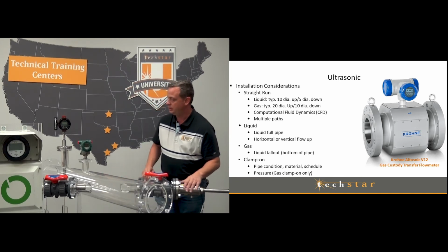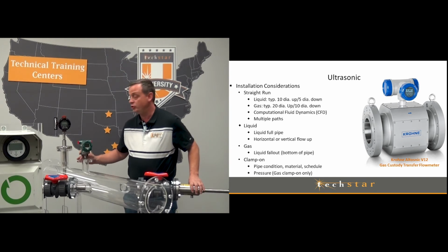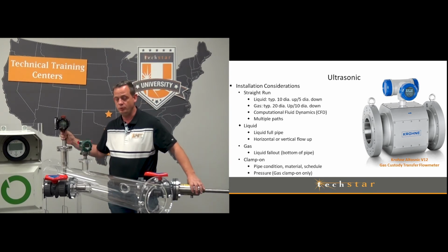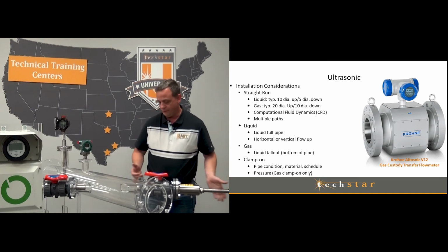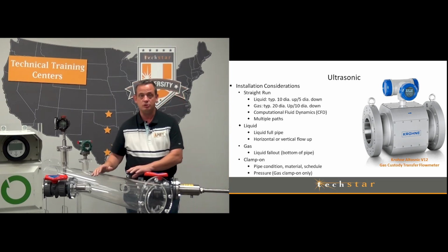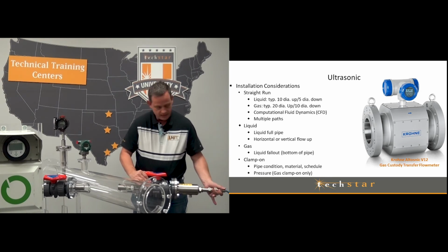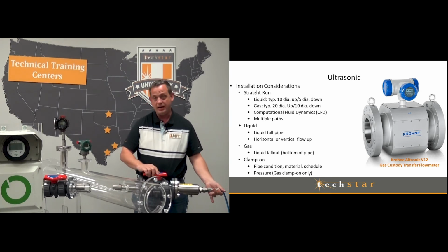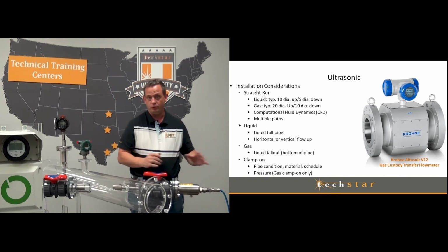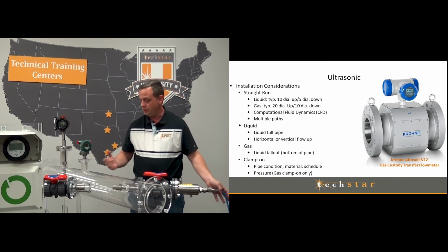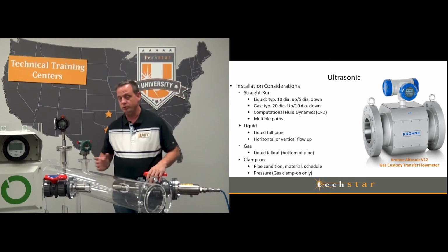So what you're looking at here is a flare meter. We have a pressure input on it. We also have a temperature input, and these are insertable. So on this flare meter, for servicing purposes, these transducers actually need to be pulled out, and then they can be inserted back into the pipe. They have a packing installed on it, and you would just shut the valve when you pull it out and open it, obviously, when you put it in, and secure it. And then typically you would do your testing on it.